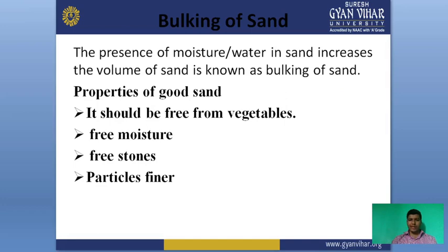As you know, sand is used for plastering and it is also used in concrete. The new process is the bulking of sand. What is bulking of sand? The presence of moisture, meaning water, in sand increases the volume of sand, and this is known as bulking of sand.